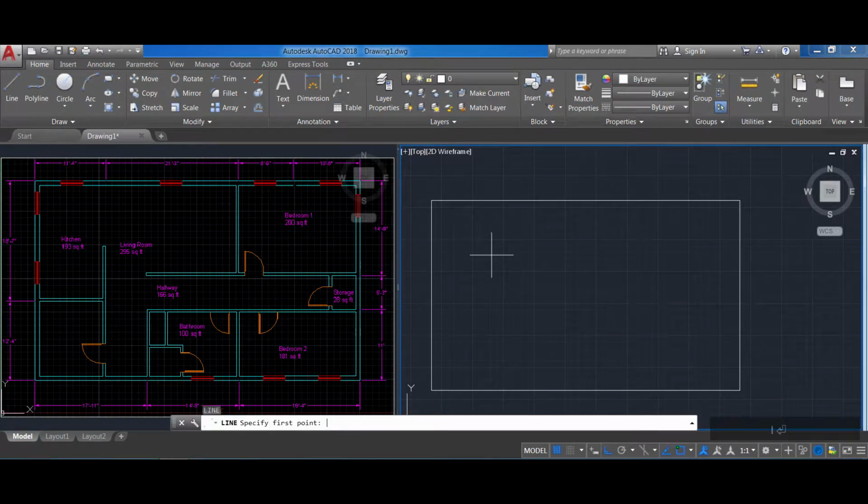So I'm gonna press L, enter, and I'm gonna go here. It could be in any endpoint really, and I'm gonna put 0 feet 5, escape, spacebar, invoke again the line command, and I'm gonna click here and it's gonna go 0.5 here too, spacebar again. I'm gonna do it here 0.5, and there are different ways to do this, but for me this is the easiest, 0.5.